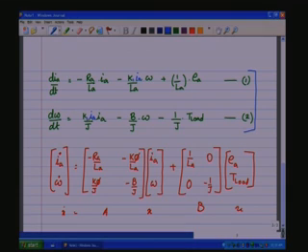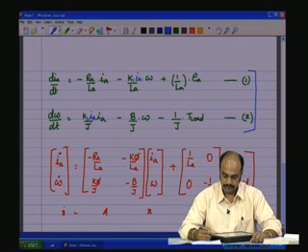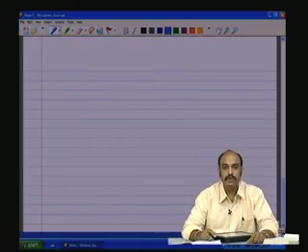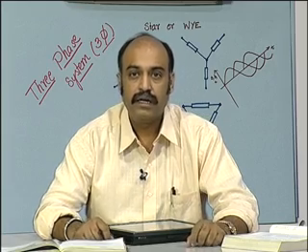motor system. So, the phi should appropriately be modified, whether it is a constant or now a function of I_A or any other variables, that should automatically be put in there, and that will give you the complete dynamic model of the DC motor in the state space form or differential equation form. Okay. So, with that we conclude our discussion on DC motors.